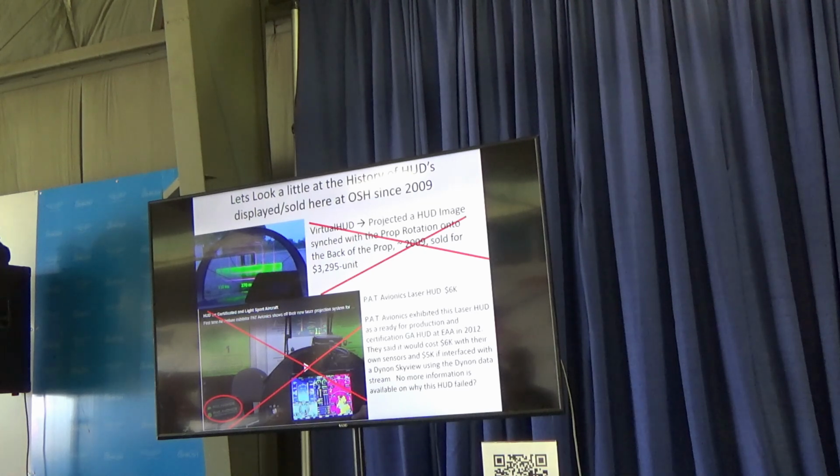We don't have head tracking, but all your HUD information is in those glasses. So you could be circling around a point on the ground, looking down there, you'll know exactly where the nose of your airplane's pointed. You'll know what your airspeed is. You'll know whether you're climbing or descending, even though you're looking down at the ground over here on the left side. So it gives you complete information of what your plane is doing without having to look at anything other than the ground and what you see in your display. So that's very usable. Would it be better if you had head tracking? Yes. But it's still a tremendous leap forward in situation awareness having that available to you.